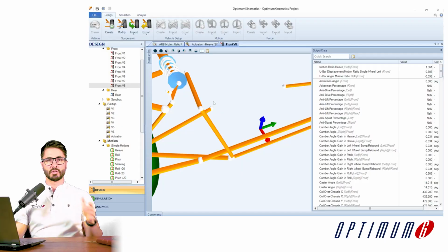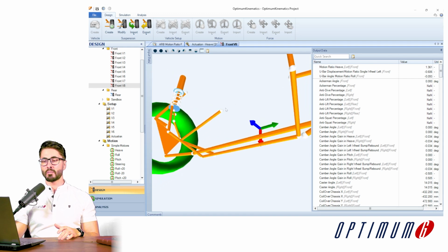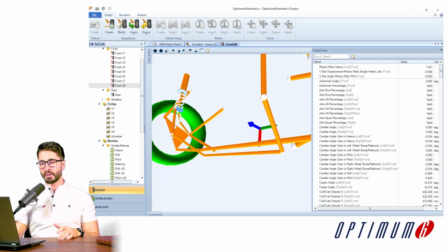Well, first, let's define our target. In the same way as the spring, we can define how much roll stiffness variation we want for every 10 millimeters of car deflection. And once we know that, this will be proportional to motion ratio squared variation. Just like in the case of the rocker, the motion ratio variation is all about the angles. So the angle of the droop link versus the rocker, or even more importantly, the angle of the droop link versus the blade will heavily dictate the motion ratio variation you have.